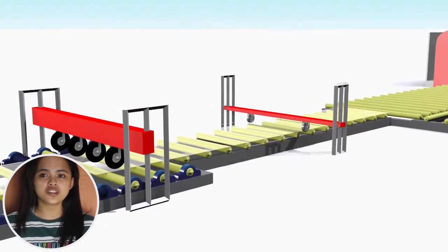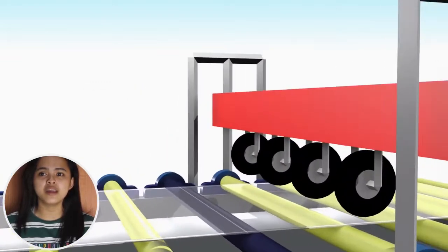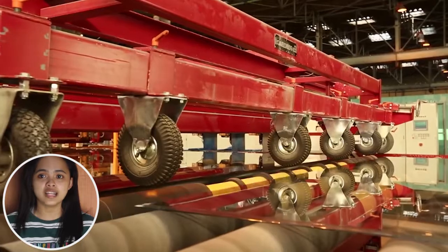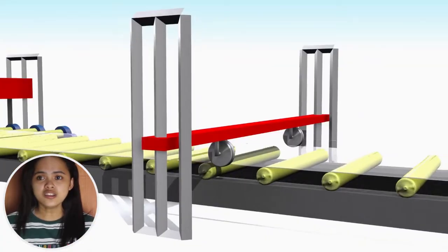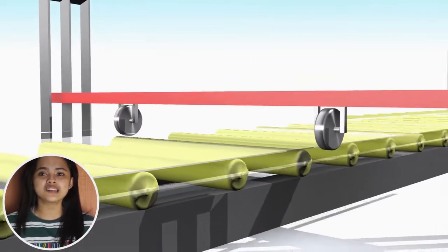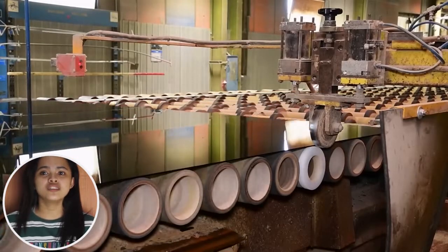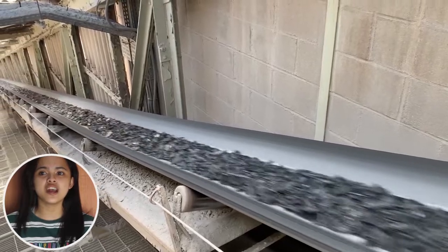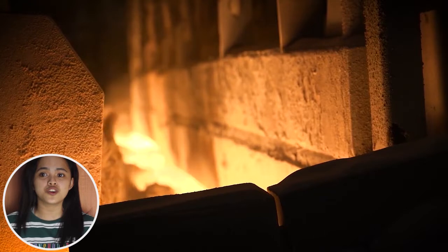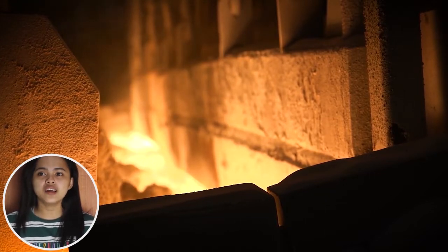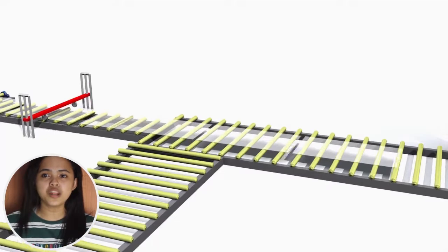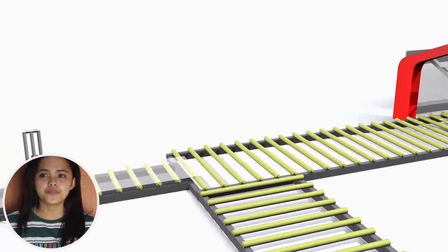The breakage operation consists in a lever effect made by an automatic breakout bar aligned with the transversal cutting line. Next, the edge rulers apply a pressure on the longitudinal cutting line to trim the glass plates. The edges, together with any glass area not fulfilling the required quality standards, go back into the furnace for recycling. The plate thus formed is carried by rolls at a higher speed to separate it from the continuous ribbon.